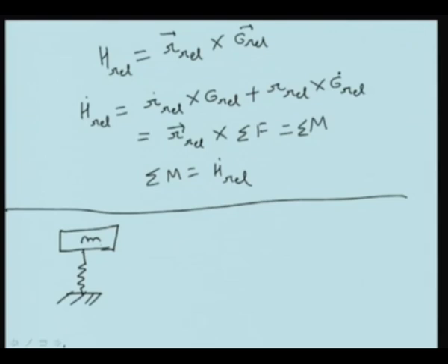If we drop a mass m from a height h from the reference unstressed position of the spring, then the spring gets compressed by delta, and mg(h plus delta) is the change in the potential energy. From the conservation of energy principle, this should be the same as the potential energy stored in the spring during its maximum deflection. At that time the kinetic energy is 0. So this gives us this relation.